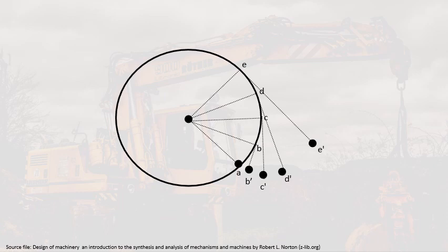So this will be the profile of the tooth that we will draw, for example, for the gear. The good thing about the involute tooth form is that it obeys the fundamental law of gearing. So again, to measure the distance AB, it is equal to BB prime. Take note that you are measuring the arc, not a line but an arc here, AB. You can use, for example, a protractor or whatever device.